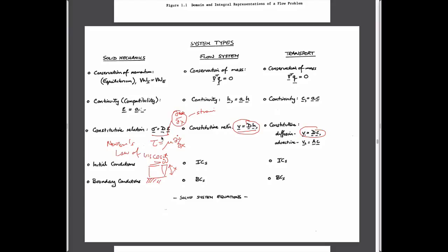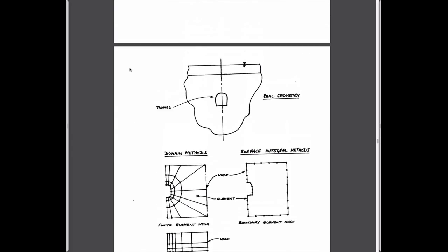And as fluid pressures change, they change the magnitudes of effective stresses, and therefore deformations develop in accordance with those fluid pressure changes. So typically we deal with static, non-dynamic mechanical behavior and link it with dynamic fluid behavior where the fluid pressures are evolving as a function of time. And so that's what we're going to attempt to do now. So I jumped ahead of where we are.